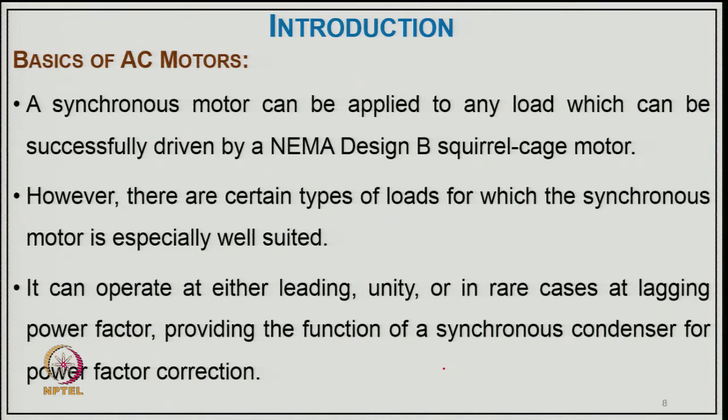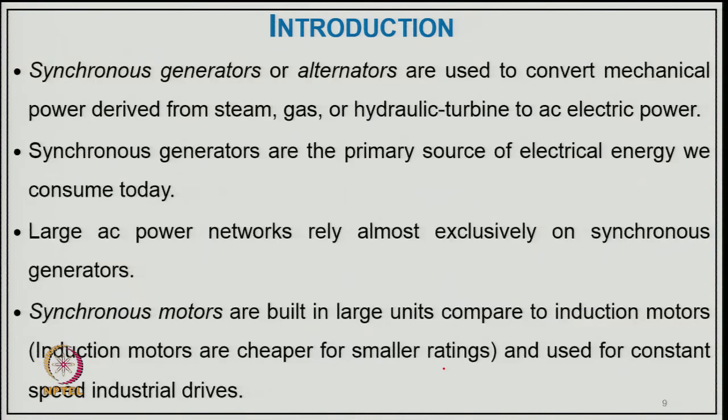However, there are certain types of load for which a synchronous motor is especially well suited. It can operate at either leading, unity or, in rare cases, lagging power factor, providing the function of a synchronous condenser for power factor correction. So, of course, this machine can work as a generator also.